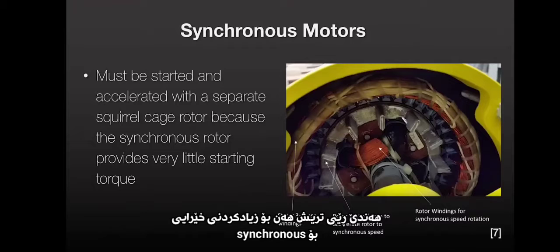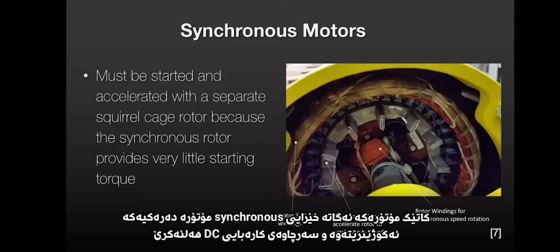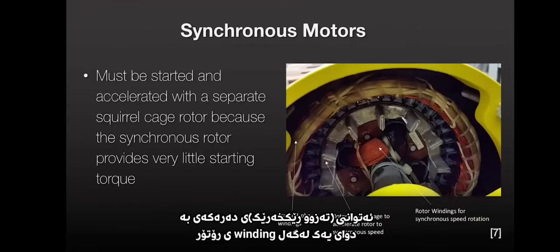There are a few other ways to accelerate the rotor to synchronous speed. You can use an external motor coupled to the motor drive shaft. Once the motor achieves synchronous speed, the external motor is shut off and the DC power to the rotor windings is turned on. You can also connect an external rheostat in series with the rotor windings, just like in a wound rotor motor.